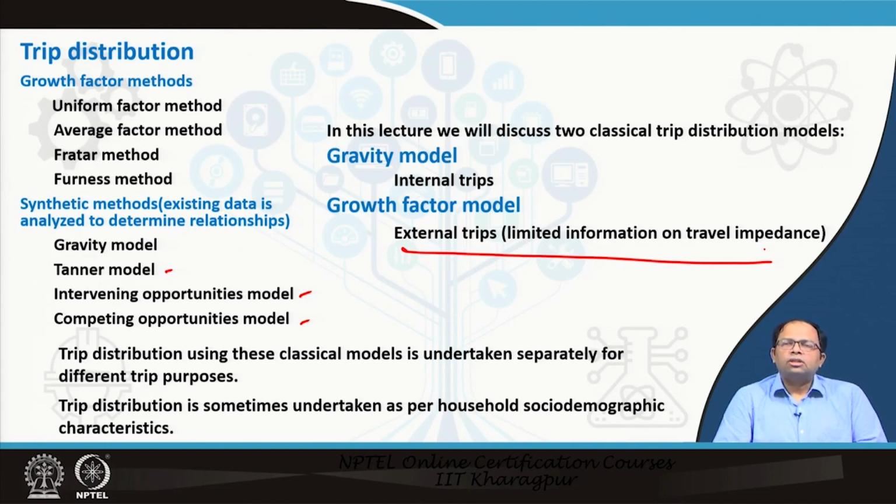So, in the mode choice part, we actually require data which shows us that different types of socioeconomic groups, belonging to different economic categories and so on, will be choosing different modes, or are prone to choose different modes. So, at the mode choice level, we need to bring the trip distribution data in a form which is also taking care of the socioeconomic characteristics.